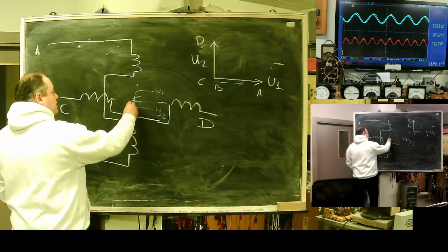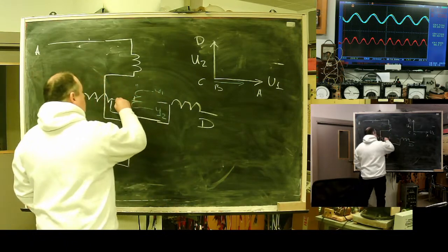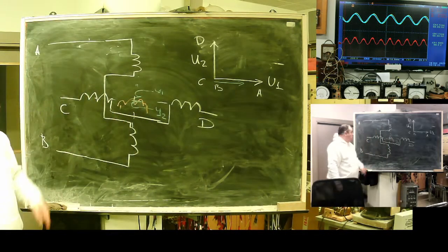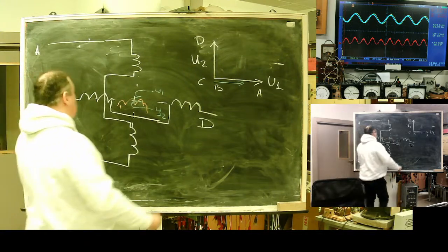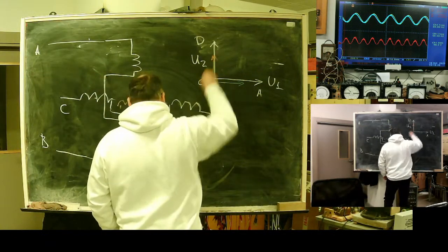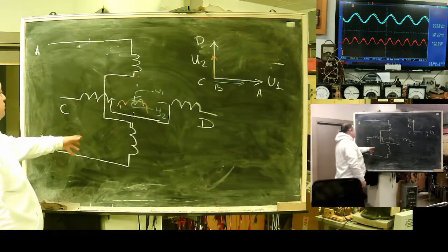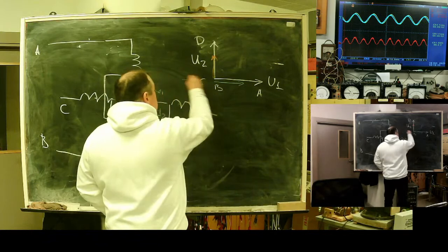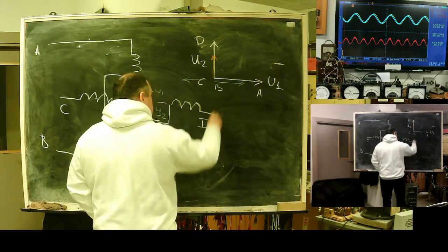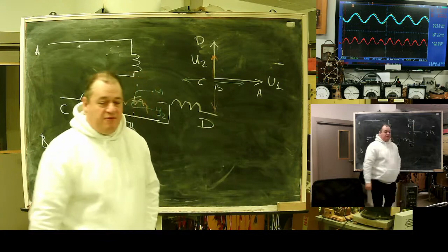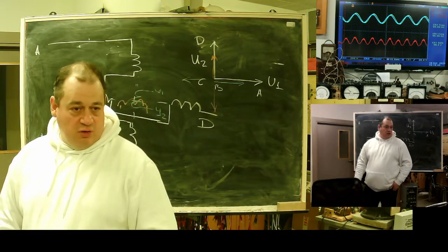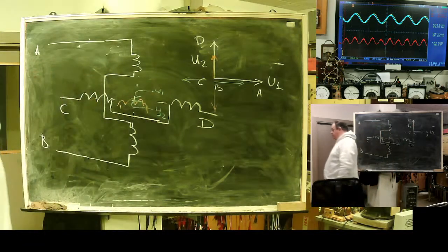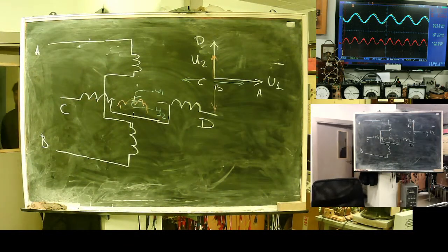If I rotate it, let's say it will be like I'm drawing in orange, if I rotate it to 90 degrees, what will be the output? I can rotate it and get this voltage like this, like this. I can have any direction of the output voltage of this coil just by turning the handle.